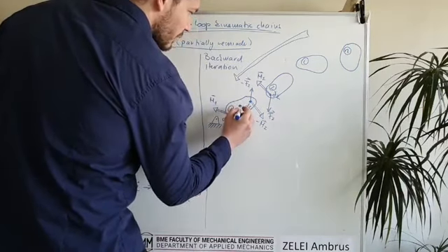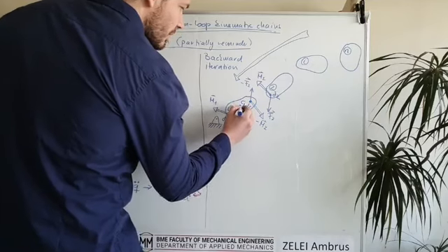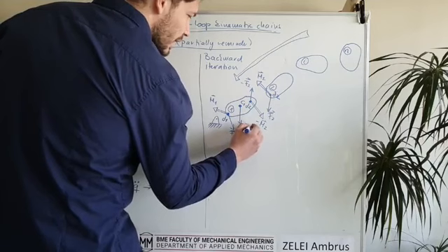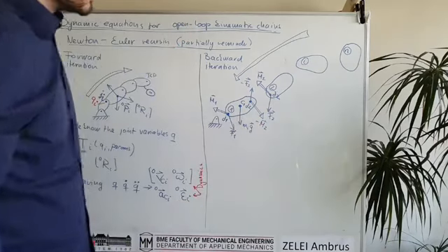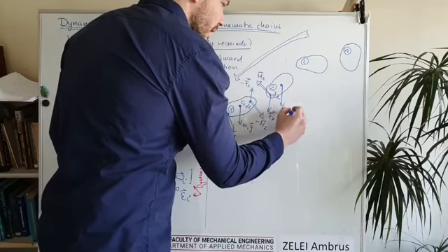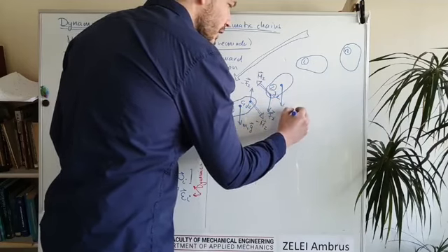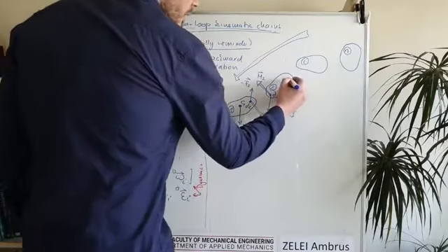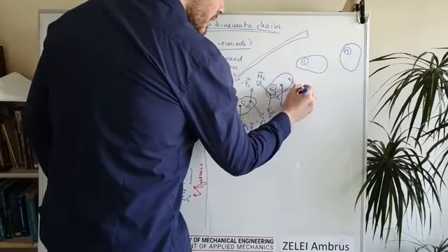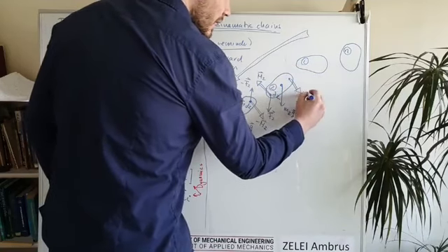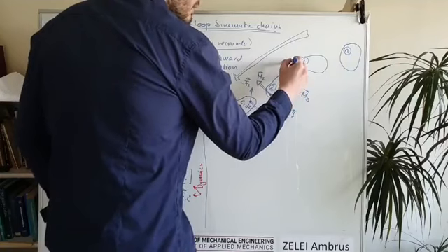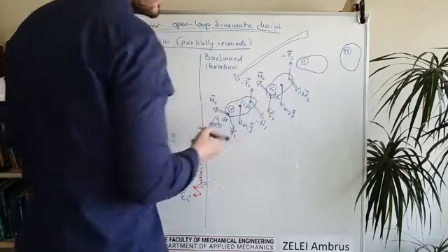external forces. So for each rigid body there is a gravitational force, so this is M1 times the gravitational acceleration. This acts also here, this is M2 times the gravitation, and of course in the second link there is a reaction torque from the third link, which is not drawn here. This is minus M3 and minus F3 and so on.